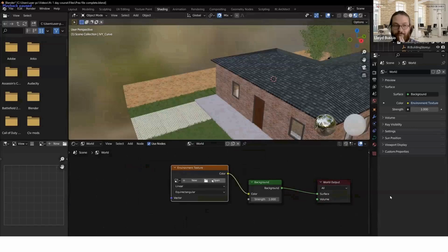So just a quick reference into this. There are multiple ways to do shading of your environments in Blender. You can use a sun, which gives you an accurate position according to a longitude and a latitude, or you can use a 360-degree photo called an HDRI, which is often used in animation and visual effects. But until Blender, I had not seen it used in architecture. What that gives you is two things. The one thing is it gives you a 360-degree photo of a surrounding, a context, which is very useful, especially when we do renders for a house.